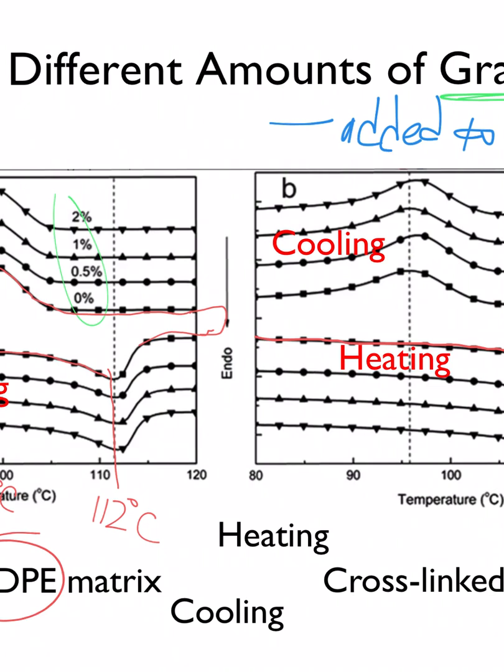All right, the cross-links are always there. They're permanent. These are carbon-carbon bonds, so you're not going to be able to change them by melting or cooling these structures. And so, as before, then we go up, and then we come back down, and we start cooling this, and we get a transition on the way down of whatever that is, 96 degrees centigrade, as opposed to 99.